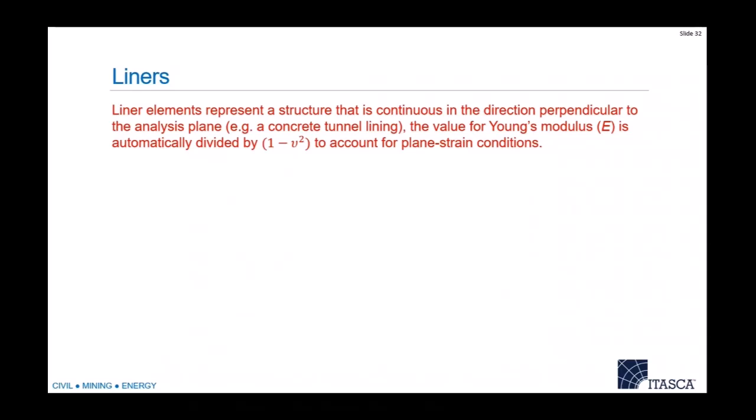So you might ask yourself, well, plane strain is the entire modeling scheme for FLAC2D. It's actually 2.5D. It basically means that you can actually get the out of plane stresses. That is not the case for structural elements. For structural elements, they are all plane stress elements. That means that the stress out of plane is always zero. And that's basically the end of story.